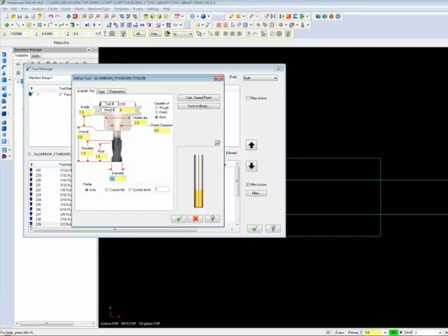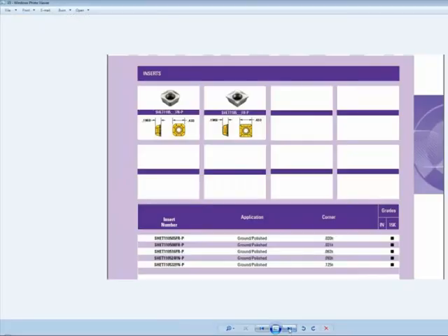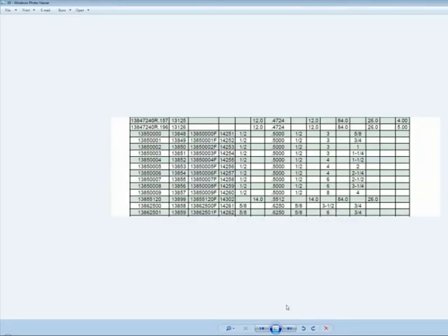Our end mills come to us from M.A. Ford, and they are Series 138. We have two 1/2-inch end mills with different flute lengths. The first has a 3/4-inch flute length, while the second has a 2-inch flute length. Consulting the catalog, we can see the end mill part number, shank diameter, overall length of 3 inches, and a flute length of 3/4 of an inch.